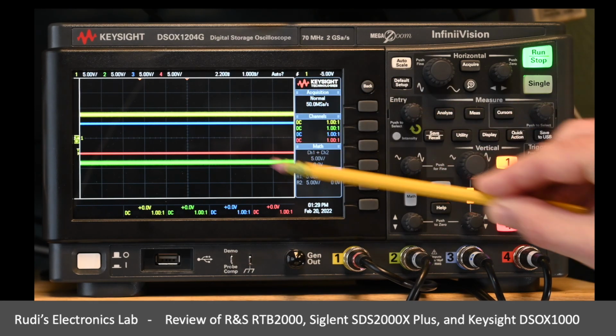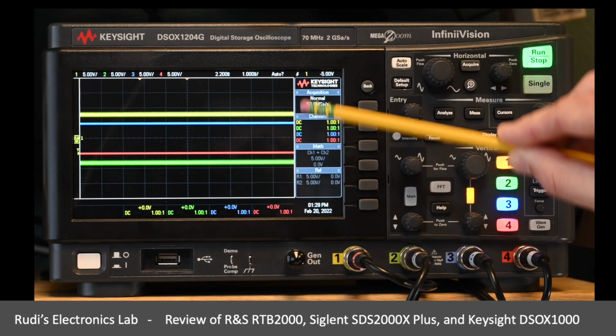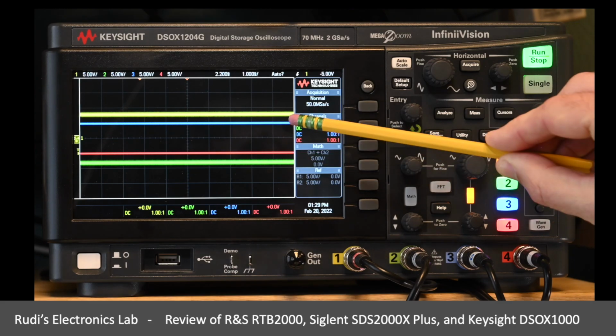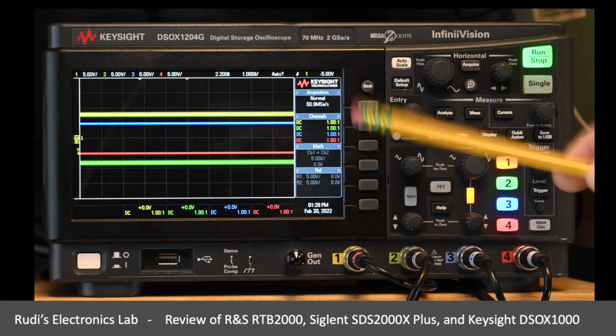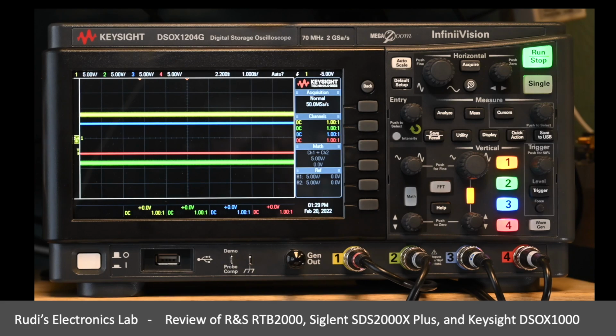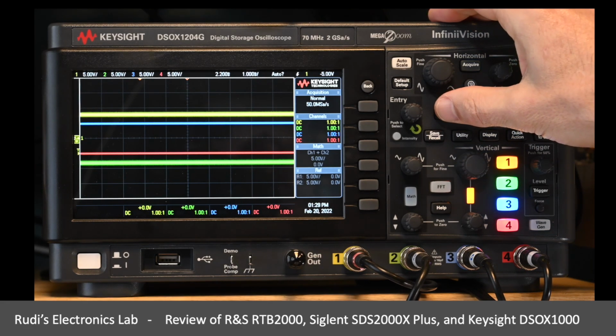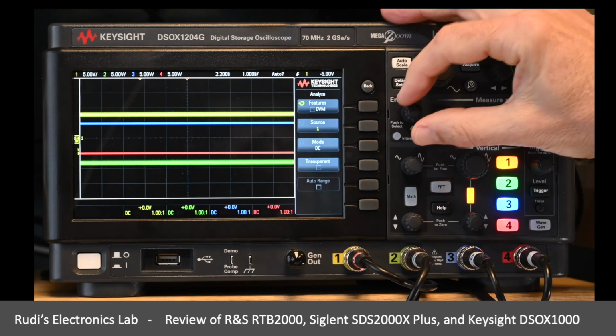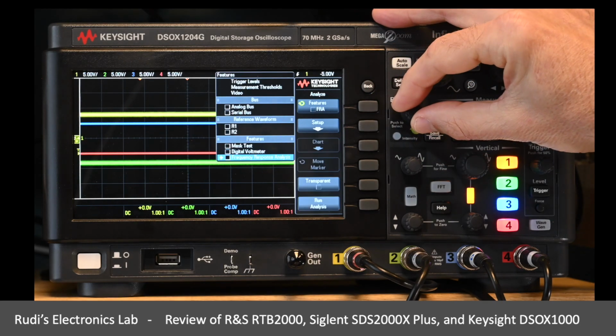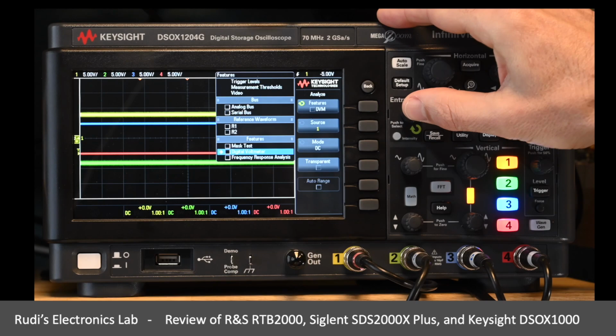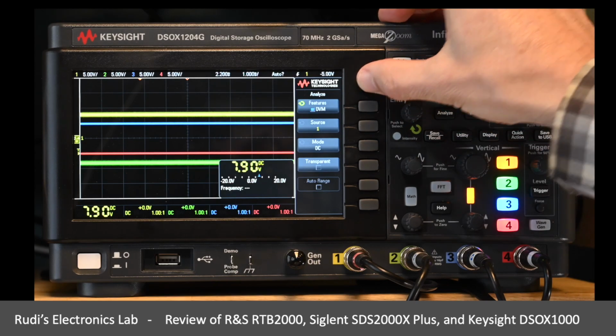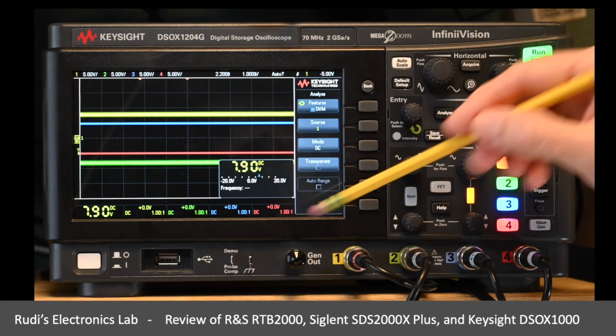Again, going to look here at these power rail signals, 8 volts, 5 volts, -5 and -8, and I put a little bit of noise on there. And now let's go to the voltmeter, and here this voltmeter is under the analyze function. I would have to go here to the digital voltmeter and select it, and what we get to see here is a window popping up.